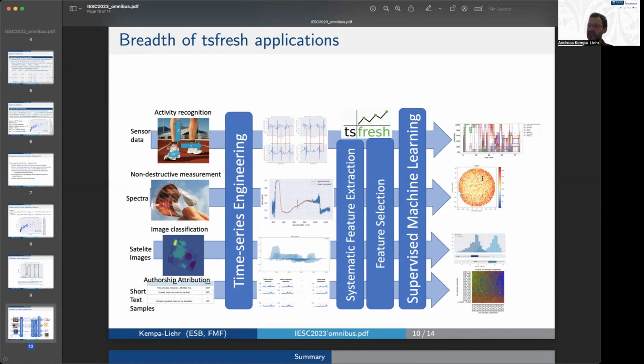which does not need to destroy the solar cell, right? If you have got a couple of calibration measurements which map these spectra to the respective thicknesses. And here this example has been taken from a spin-coated organic solar cell. You clearly see that at the rim, the thickness is higher compared to the center, and there are also some defects, right? These blue points here, where no coating really stuck to the surface.